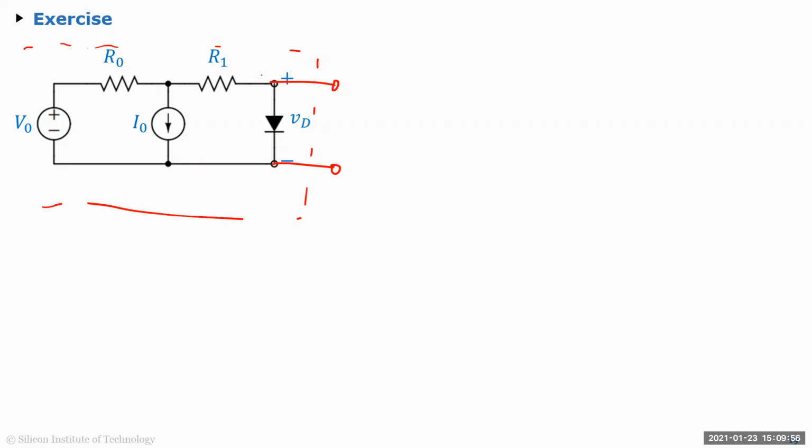But what you can do is find the Thevenin to the left of this, right? It still helps you a lot. Typically this will just be to find the current through the diode. Let's say you're doing an LED driver, you have the circuit on the left, and you're just trying to figure out how much current is going into the LED, the diode. If I take this, I can't apply KCL, KVL, or any of the linear network theory.